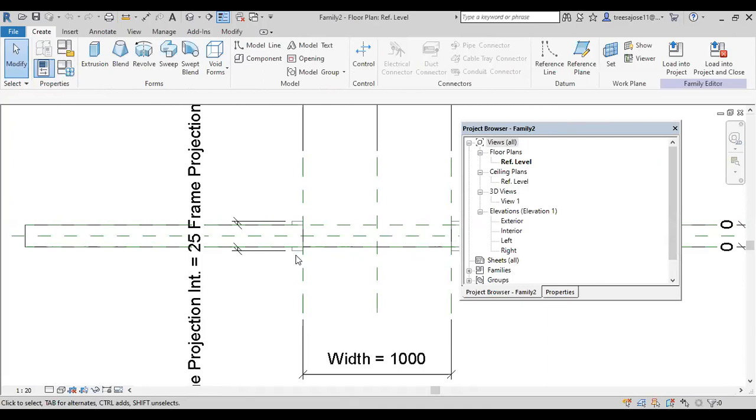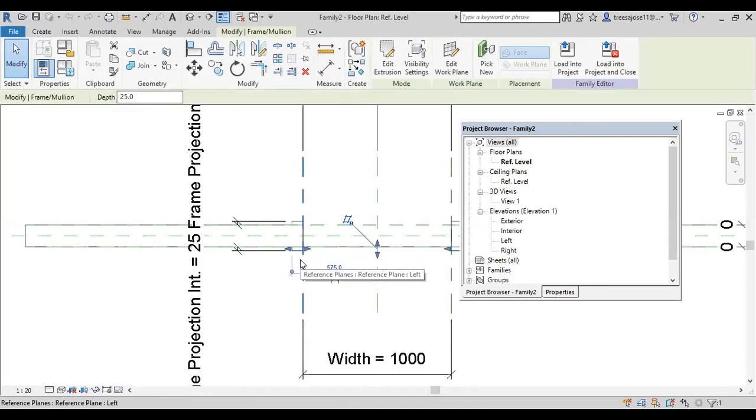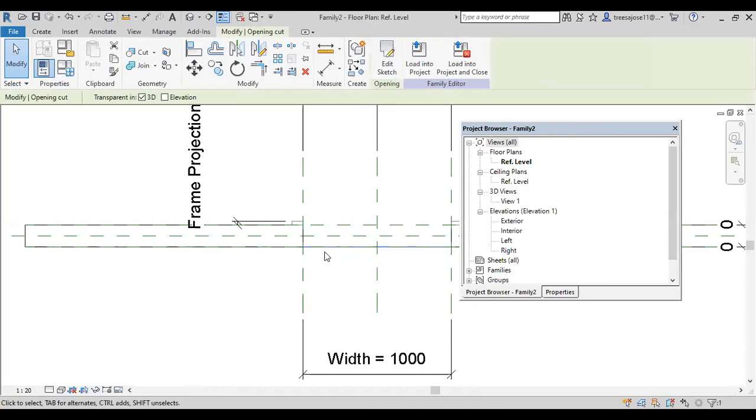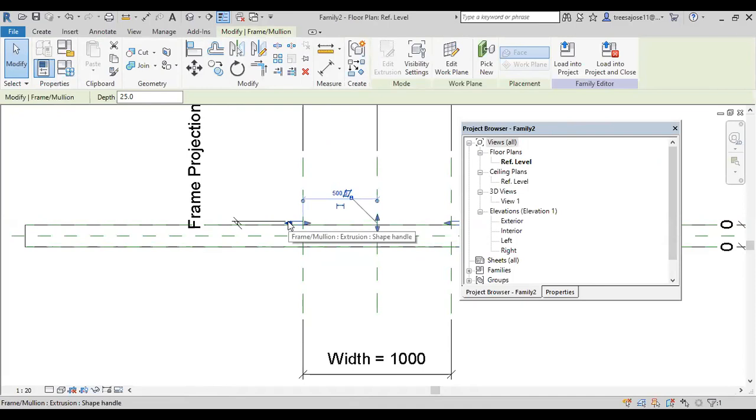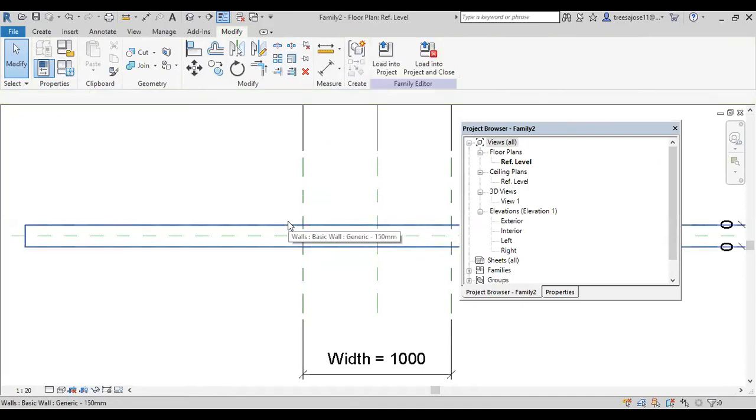Okay. The default frames and door will be there. You delete this one because I want to create my own door design. You select and delete all this. Actually, the wall will stay, because the door is mounted only with respect to the wall, so don't delete this wall. If you delete that wall, we don't get the output. You retain the wall, then make the unit.